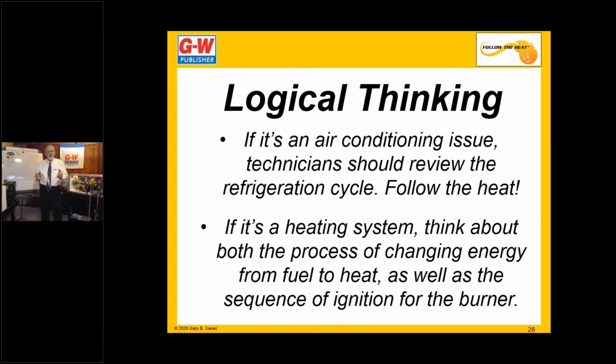Check the thermostat. How many times have we found a situation, especially in residential and light commercial work, which I very seldom did, where people mess with the thermostat? And we find that the only problem is the thermostat. So think logically through the system. Start at the beginning and think logically through that.